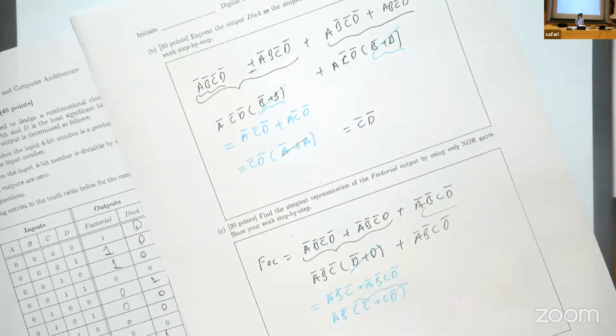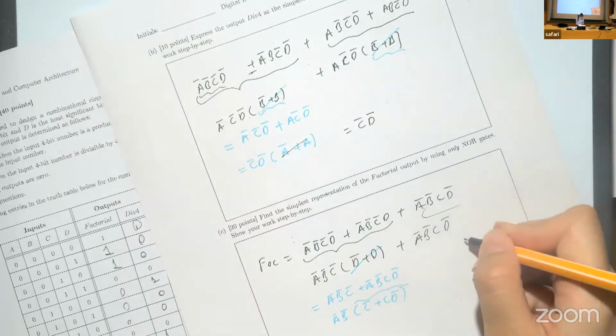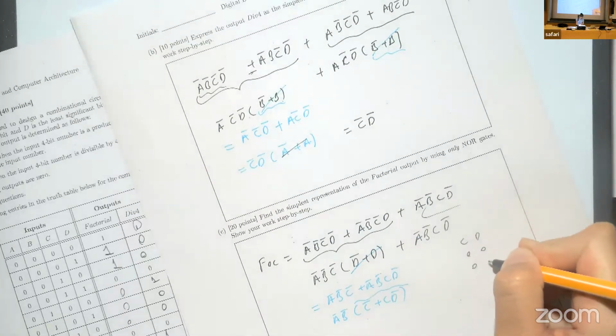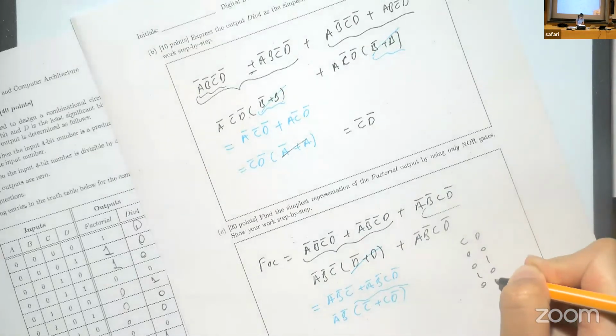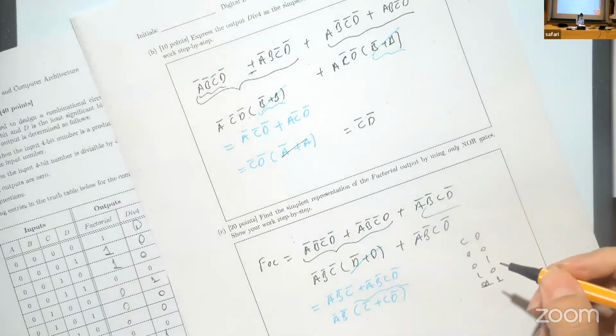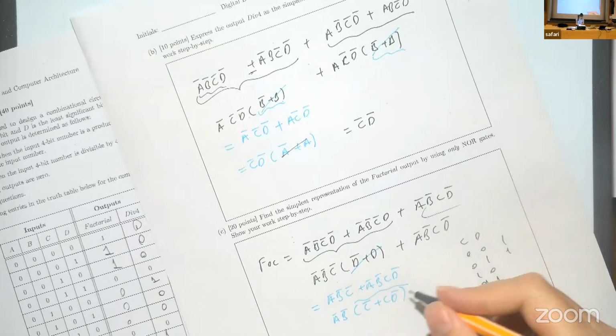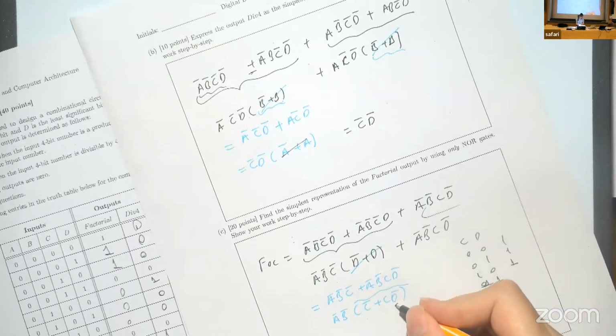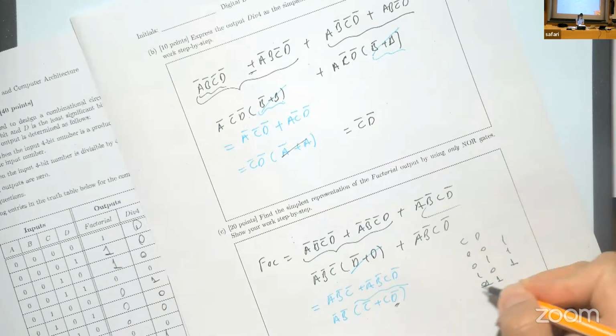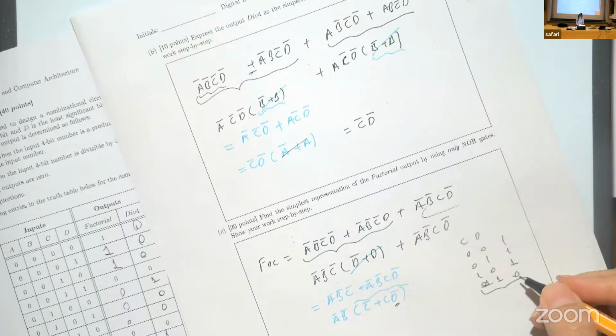If you cannot see how to simplify this part easily, and you have only 2 inputs, you can just come up with a simple truth table for C and D. From the expression, if C is 0, the expression is going to be 1 for sure. And if C is 1, D also has to be 0. And if both of them are 1, you get 0. That's why you only get 0 when both of them are 1.